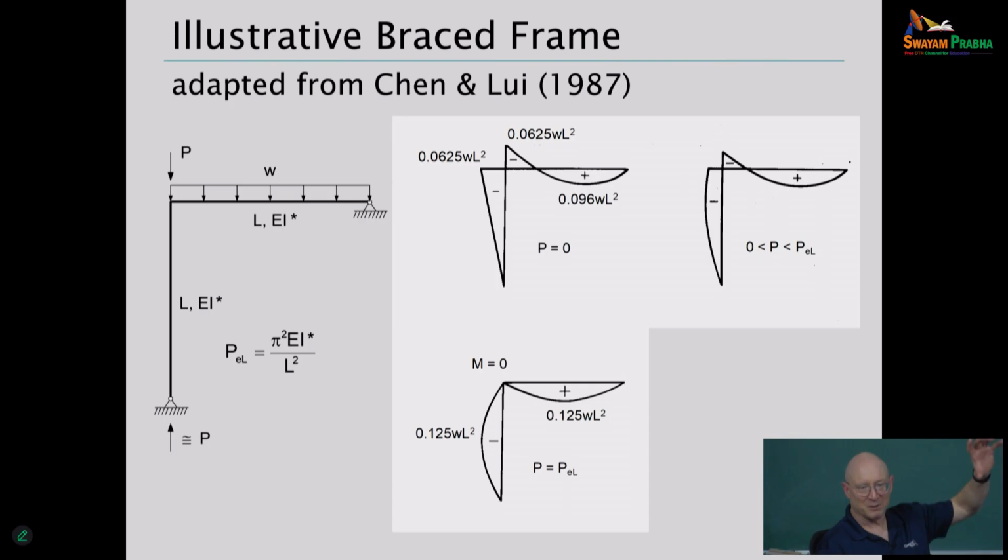But it is taking some moment from connectivity to whatever is up at the top. And so you can have a situation like this one where you may have designed that beam saying, oh, I have restraint from the column. No, you don't. You just lost it all.